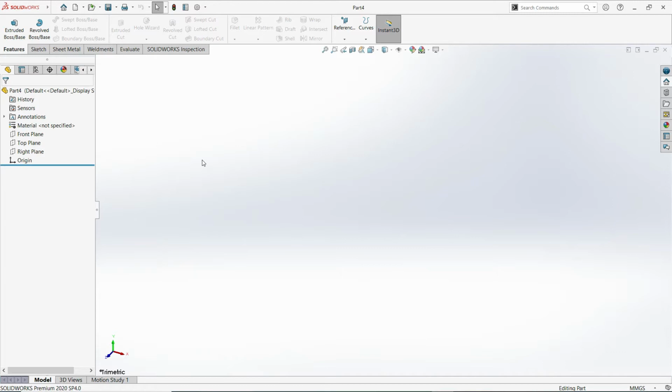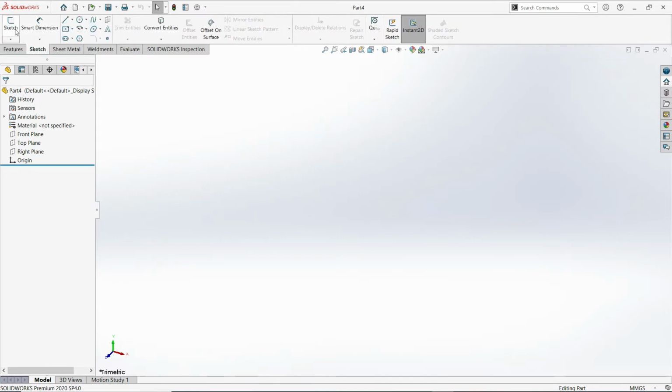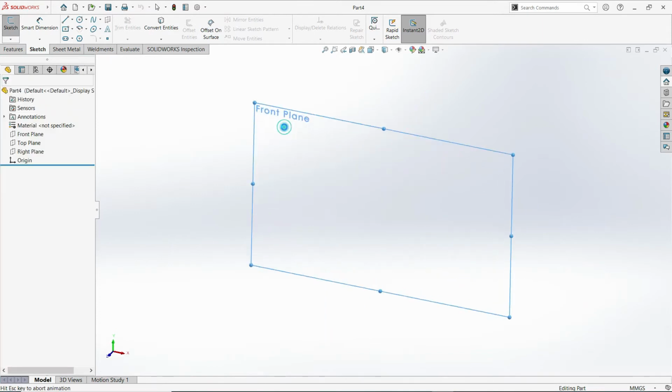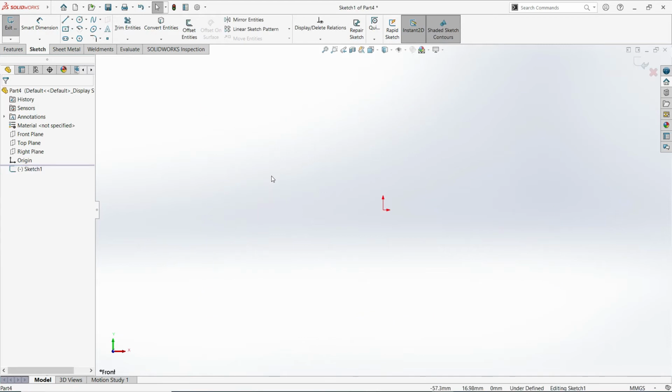Again, when starting to draw the profile, you need to view the profile itself. So I just select the sketch, then the sketch tool. Then you have your three planes. Make sure that the plane is highlighted, for example, the front plane is highlighted now. I could select this one, and that plane will be perpendicular to your view for easy drawing.